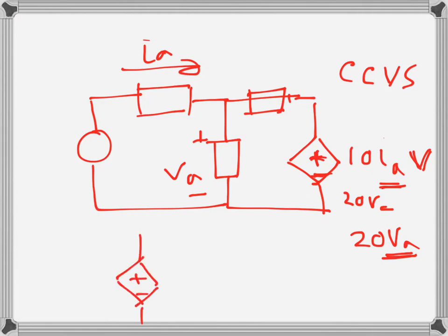So this is the voltage source, voltage controlled voltage source or current controlled voltage source, and this is a current source, which can be voltage controlled current source or current controlled current source. The source is a current source, but its value can be defined by the current of another branch or by the voltage across another branch. So we can have a similar scenario.